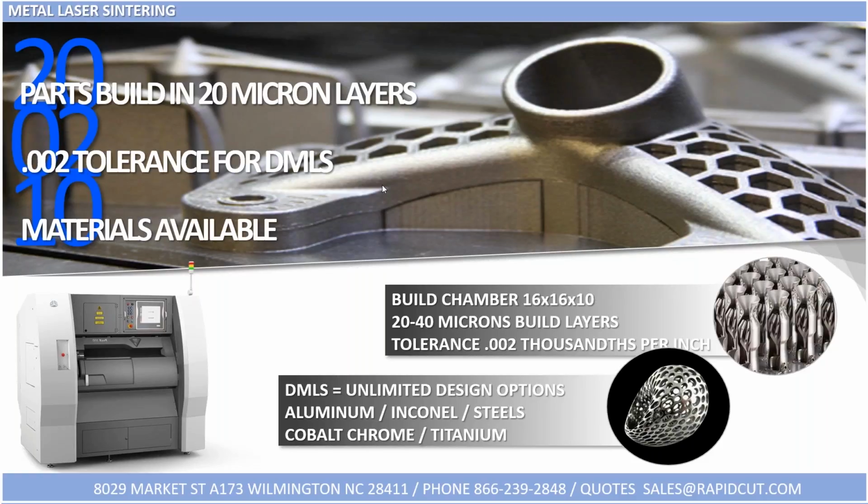Fantastic, very, very tight layers. As you can see in the examples here, these are straight off the machine, and you can expect this finish that's really consistent with a die cast part. 2 thousandths tolerance for this process. Unlike the plastics, it holds a much, much tighter finish. There are 10 different materials available: different varieties of aluminum, Inconel, different steels, cobalt chromes, and titaniums.